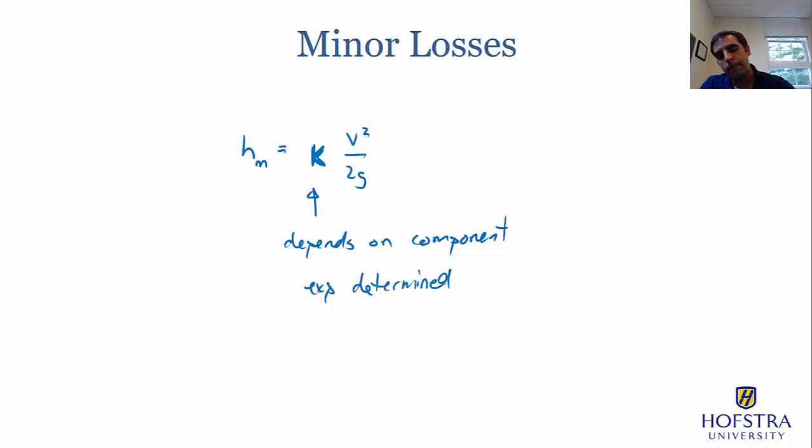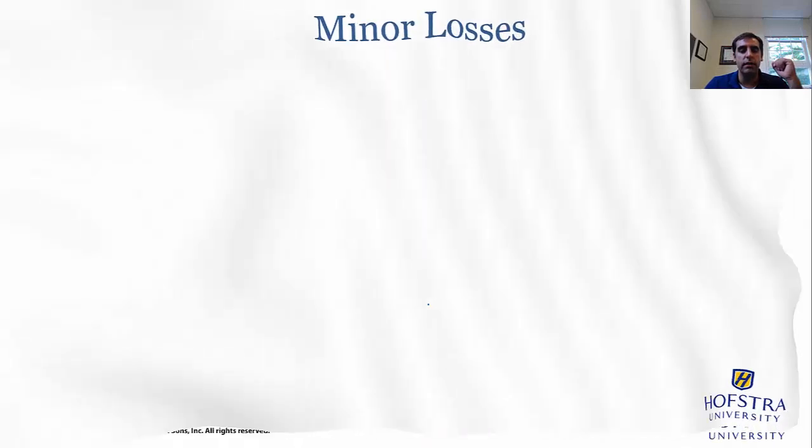And so we're going to try and experimentally gain this, and we're going to compare it to tables that you might find in textbooks or produced by ASHRAE, which is the professional society that looks at heating, ventilating, and air conditioning systems, which often do these types of calculations. All right, but the idea here is anytime you have flow not just going in a straight line or down a tube, it's going to take some energy to make a turn or go through a valve, and so that energy manifests itself in a pressure loss, and of course overall as an energy change.